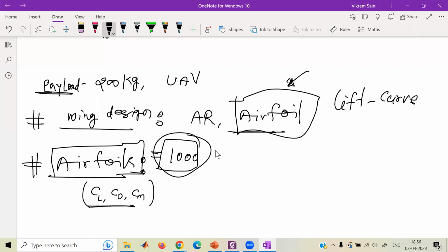They will see the bending loads on the spars and the fuselage section analysis, but that's not useful to me. That is useful for them or the manufacturing group. What is useful for me as a flight mechanics group? What information do I want from them when I want to perform some simulation of the aircraft? I want to fly this aircraft. All of the maneuvers that you study in the books, we want to perform those maneuvers and actually check whether the aircraft is able to perform as we desired during the design phase. So what are the quantities, the numbers that I need from the structural group?